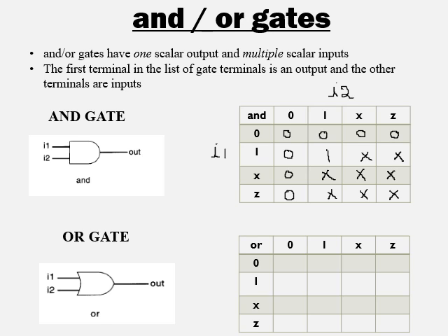So these values are resolved based on the strength levels. You must have studied that in Verilog there are 9 strength levels that a variable data type can take. They are arranged from weak to strong. Some signal strengths are weak and some are strong in comparison. So when a strong signal is ANDed with a weak signal, the weak one is overridden by the strong signal. So based on these, the signal values are resolved.